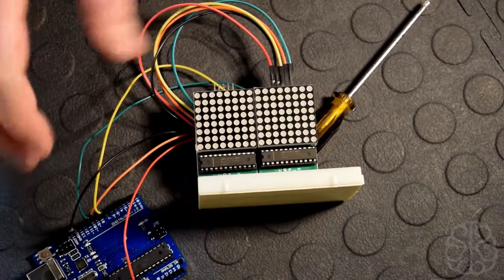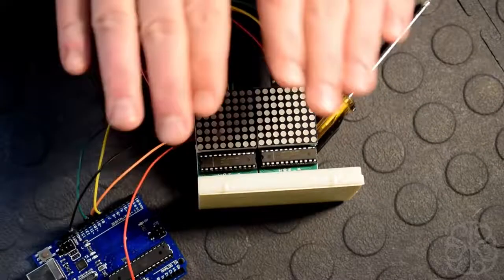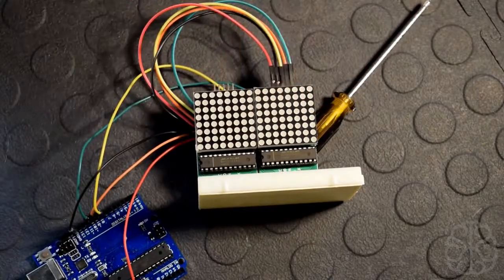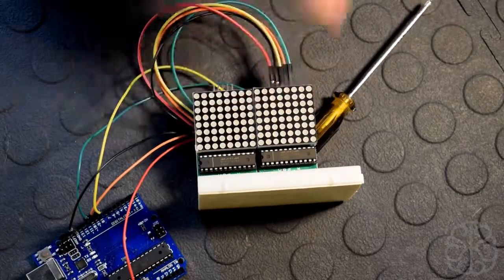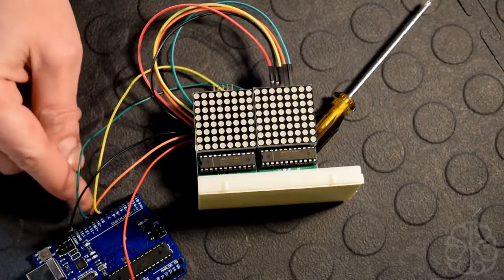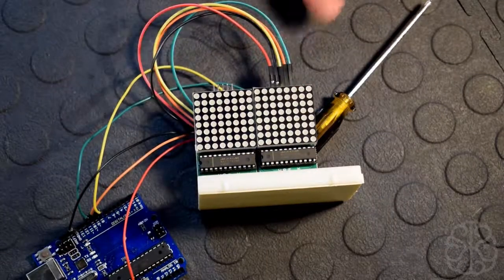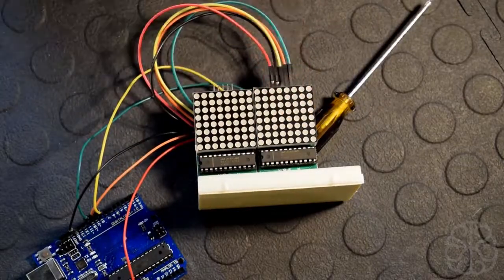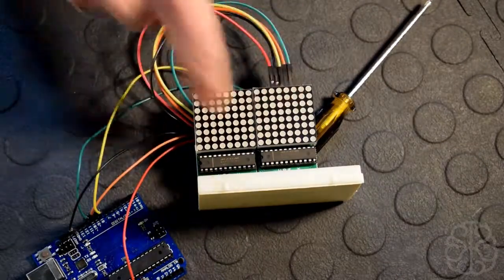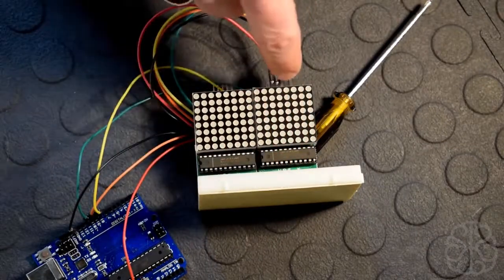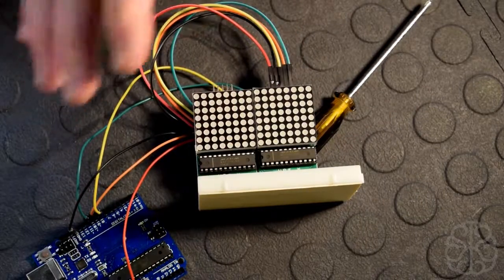So the connections are not too hard. I got my voltage and ground going. It's on the back side because I'm using breadboards, so they sit nice and snug together. So voltage and ground to this one right here. And then I have pin 8, 9, 10, which is connected to DIN, CS, and clock on the back side. And after that, I'm just taking this little jumper cable here and going to the back of this one. So basically they're linked together like that. Like this is the in, this is the out. So this one goes from the out to the in of this one. So basically that's all we need to do here.